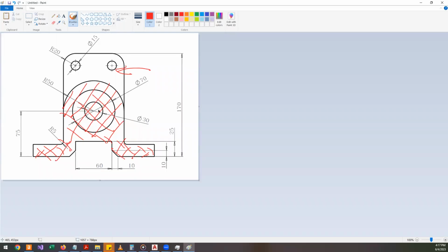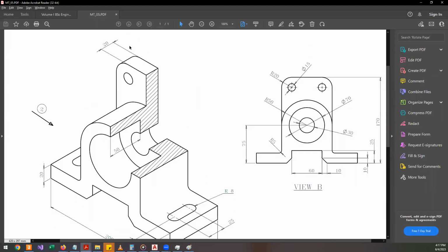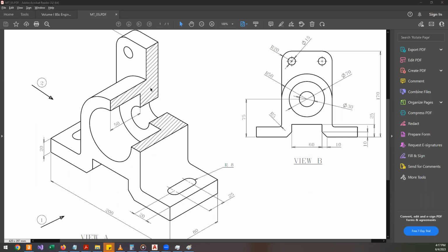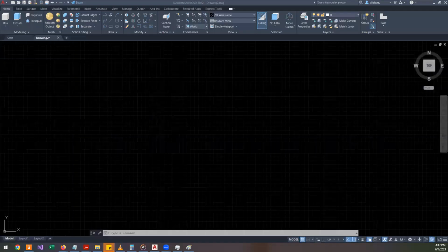If you remember last week's lecture, if you have those kind of properties, then you can simply use the extrude command to model that object or part of that object. Afterward, I will use the same extrude command to get the bottom part. That's going to be my approach here.